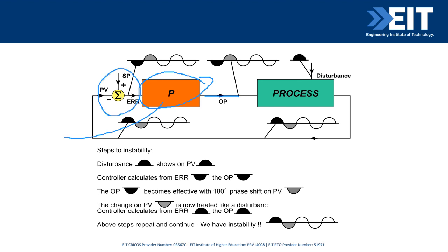The set point we've already spoken about is the target value. The process value is the variable that you're measuring. It could be a temperature, pressure, level of a tank, who knows. And then you've got the output. And then, of course, this is the process. This is the animal that you are trying to control.